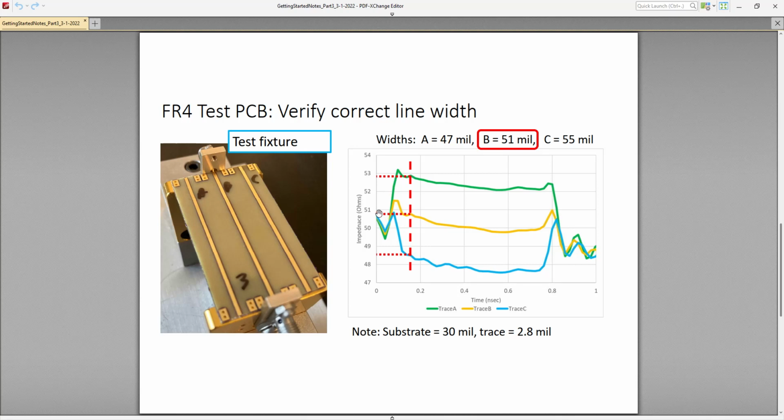The way you find out what the impedance is, you go right behind the connector and take a snapshot. You can tell that the boards may be a little bit high. The 50 ohm board may be 50.5 ohms, a little bit higher than that, but it's pretty close. It is a little bit high, which means that my guesstimate for Dk of 4.8 may be a little high, but we'll check that out further on.